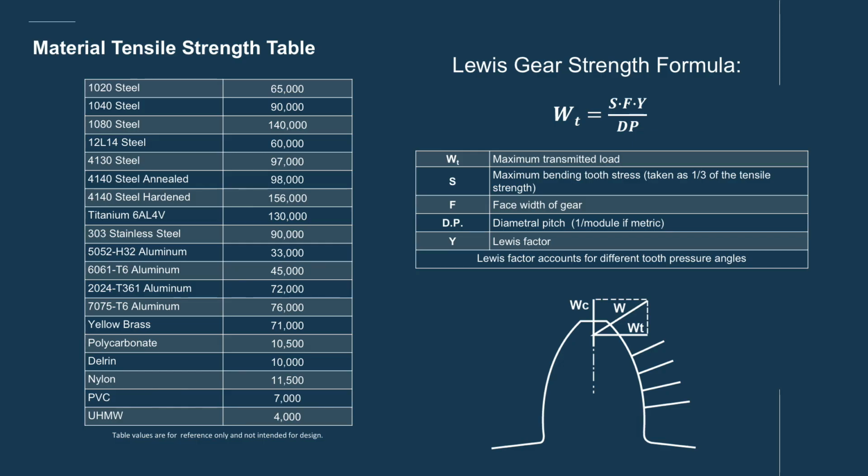The table on the left of this slide gives general properties of the materials most commonly used in gear applications. Selecting the correct material is of critical importance, as is selecting the correct material combination. Choosing poorly here can result in high costs. For example, the material may have too high performance capability for the application. Or, in some cases, a seized gear set, where improperly mated materials cause actual welding between the gears as they slide.